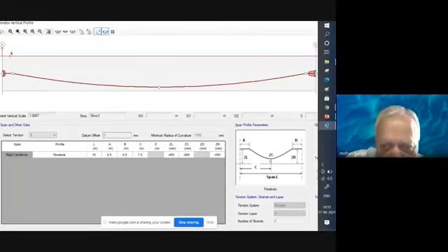So here you can see that the nomenclature is shown at the right hand corner over here. At the center, whatever is the distance, that is indicated as ZC, and that you have to define as minus 800. Now I have this beam whose depth is 900. The datum is at the top. You can see the red line. Can you see the red line?